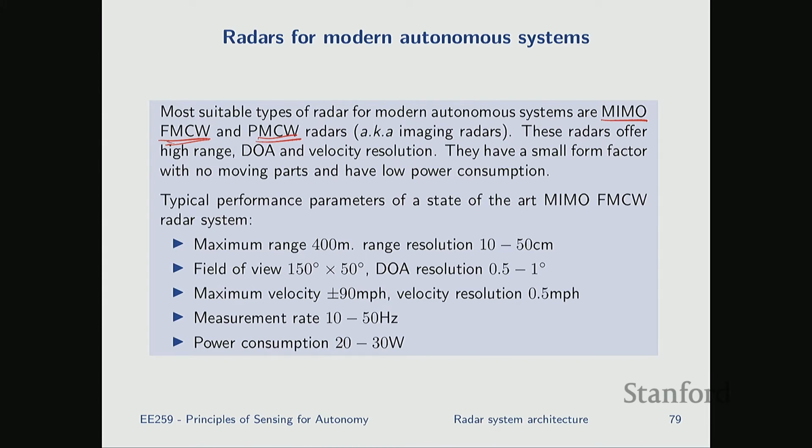Now, between FMCW and PMCW, today almost 99% of radar systems that are commercially available are FMCW systems. There are already integrated transceivers available, and they're shipping in large volumes. PMCW, I really personally like the idea. I think it's a better architecture, but for practical reasons, today these systems tend to be more costly to manufacture, and because of that, most manufacturers picked up basically FMCW as a technology to focus on.